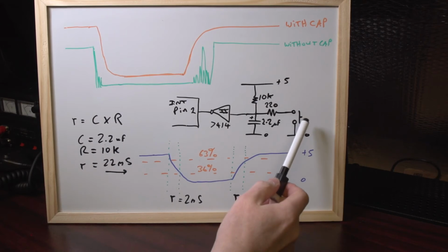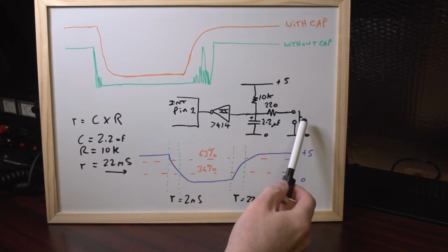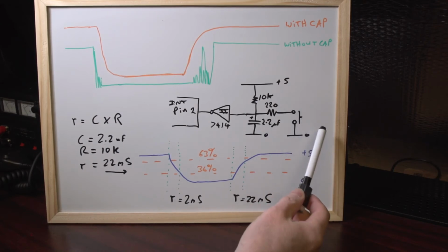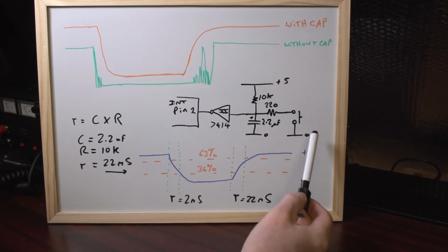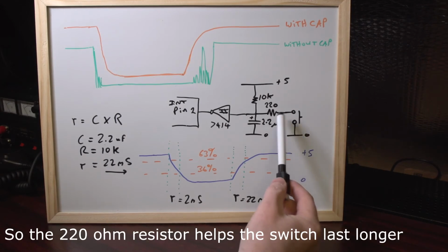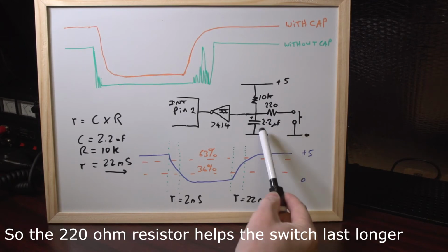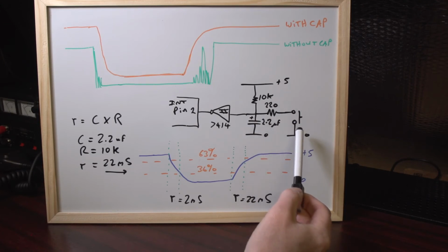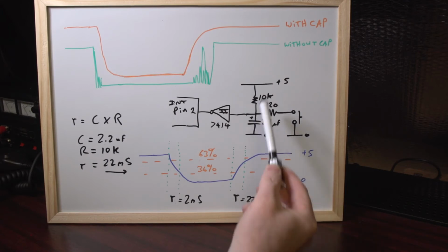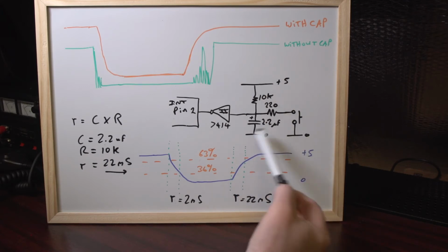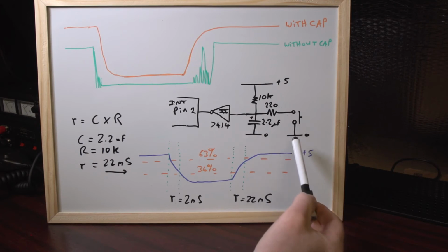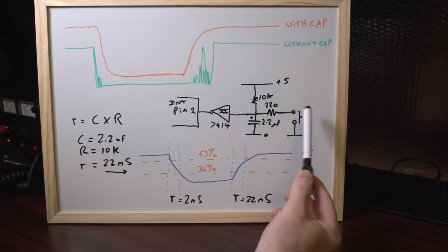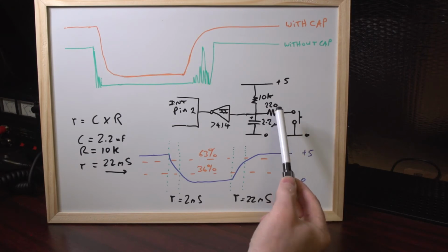But more importantly, it's going to stop the button from being destroyed over time, or let's say degraded in its performance, because what's happening here is, without that resistor, you would be discharging the capacitor's energy straight through the switch down to ground. You could have a good few milliamps, possibly, I don't know, maybe even 200 or 300 milliamps, who knows, from a fully discharged 5 volt rail capacitor through the button. You've got quite a few milliamps going on there, and because it's a dead short, the current is very high. So this resistor is twofold.